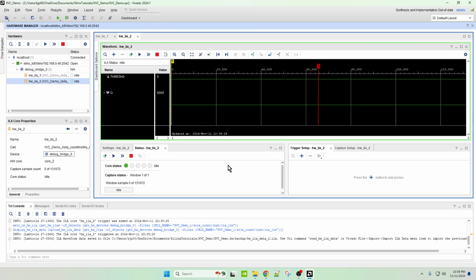I mean, this is a really awesome thing to be able to do, and it's just wild to me that there's not any good instructions on how to achieve this. I've only tested this on the Zynq 7000 series stuff. I read somewhere that the AXI to BSCAN debug bridge doesn't work on the UltraScale MPSoCs, but I'm not sure.